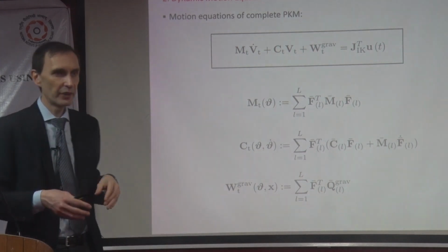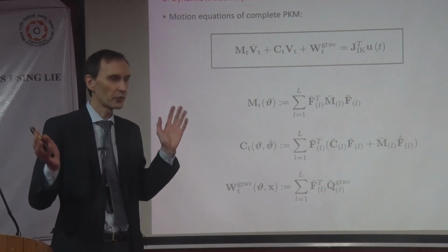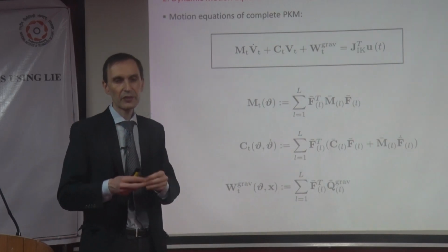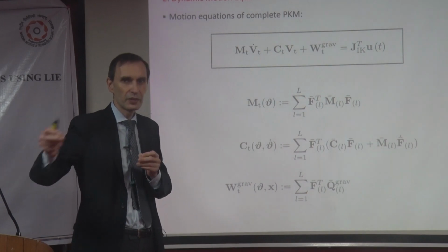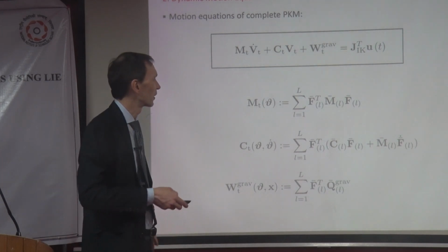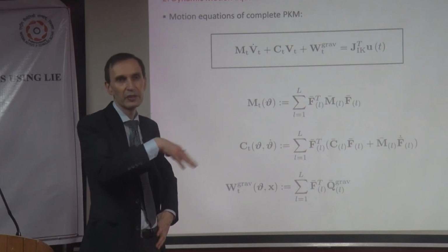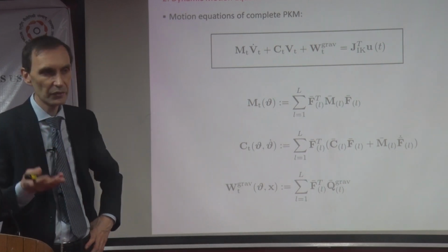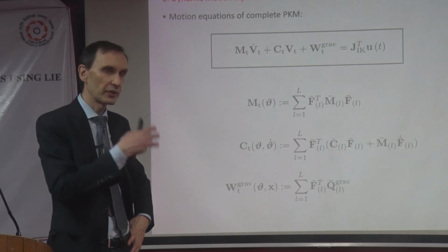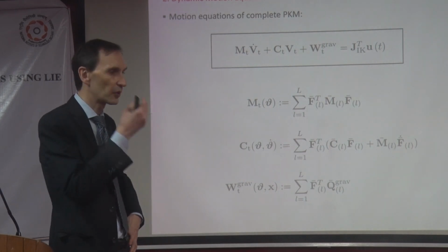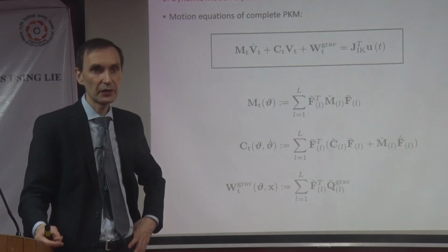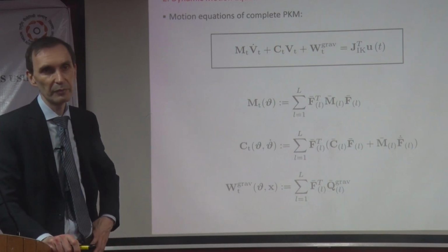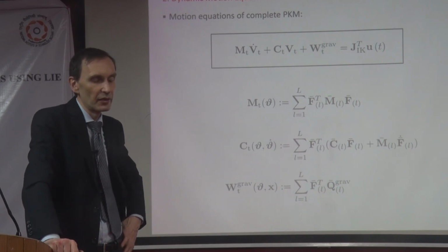If the model is perfect, there are no disturbances, and your encoders are super good. Of course, it's not perfect, but it gives you a very nice steering towards the trajectory that you want. And then, of course, you have to close the loop with the PID controller. But any linear controller is linear, and we are having a non-linear system. This is also called feedback linearization, so that you linearize your non-linear system by using a feedback loop. Or let's say feed-forward.